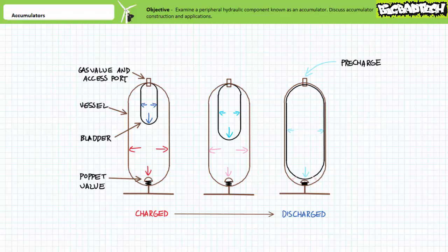Not just any gas can be used for a gas-charged accumulator. Dry nitrogen is the gas of choice because it is inert, meaning chemically stable, and in contrast to air mixed with hydraulic fluid vapors, has less of a tendency to explode. Always a desirable characteristic. Always charge gas accumulators with dry nitrogen or another inert gas and follow manufacturers' recommended procedures when doing so. We'll discuss precharge pressure and its influence on capacity in a moment.